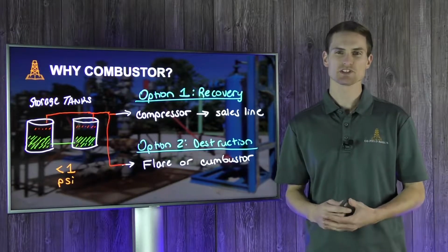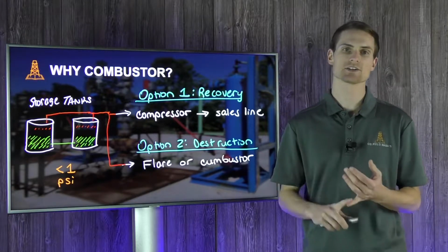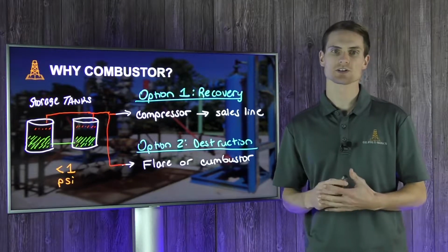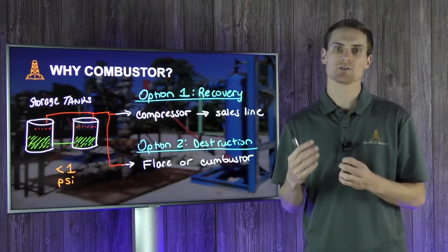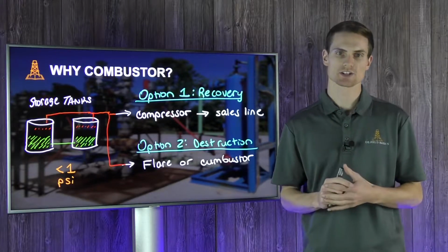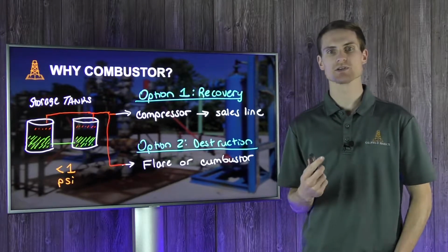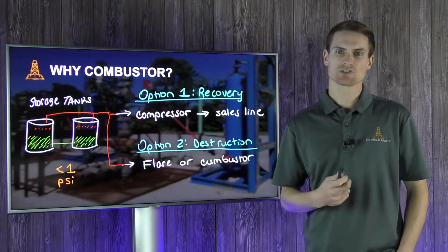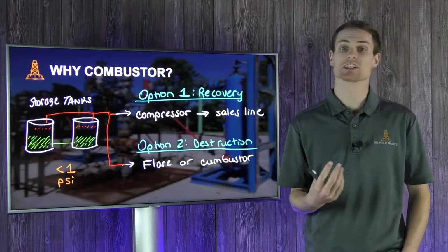Typically, flares are going to be cheaper, but they also don't commonly do as good of a job when you look at and compare destruction efficiencies with that of an enclosed combustor. Enclosed combustors are also more precisely engineered for specific flow rates, composition of gases, and line pressure. It is common to see more combustors and flares in states that are more stringent, such as PA, West Virginia, Ohio, and Colorado. And in states that are more strict, you might only be allowed to have an open flare on production facilities in a few particular cases.